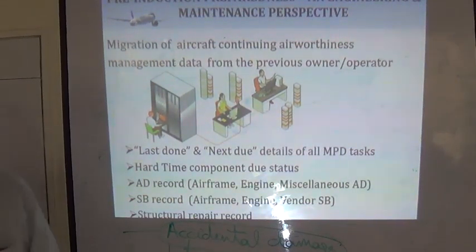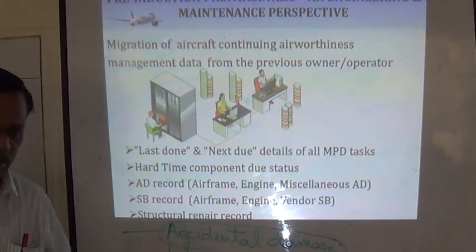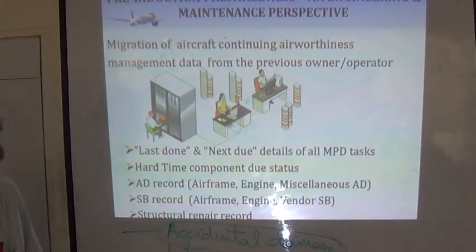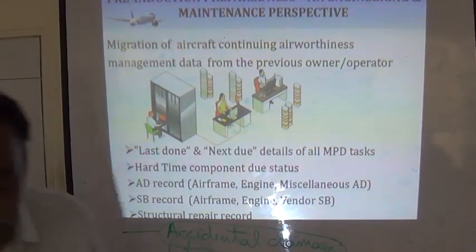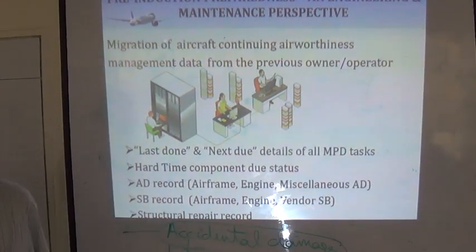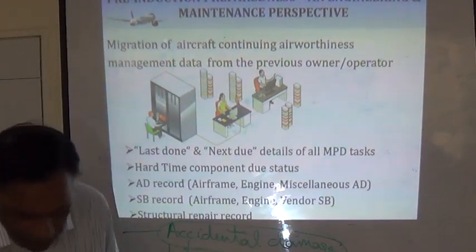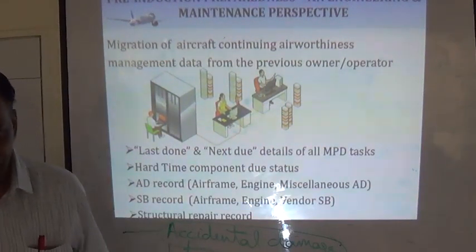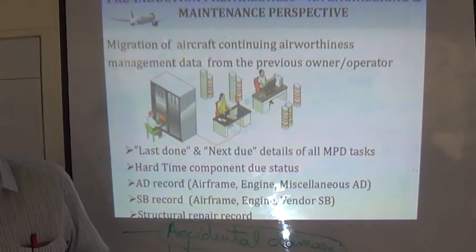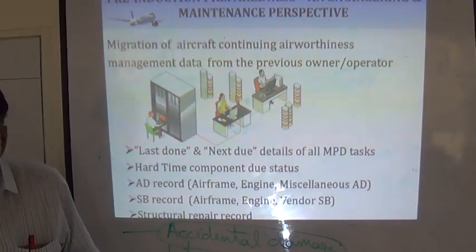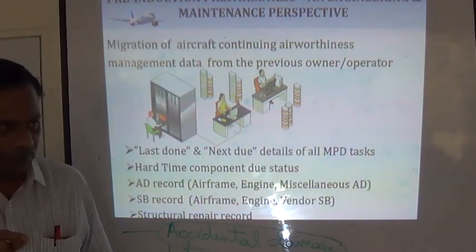Like there are some areas, even if you send the aircraft for a third level MRO check, there are some areas still undetected. And most of the time it is the toilet floor. The aircraft has a toilet, and under that there is a floorboard, which we stand on. Sometimes this toilet cleaning fluid is very corrosive.